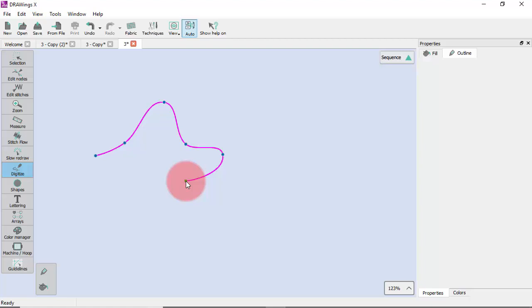While creating outline shapes, you may want some shapes to be embroidered together and others to be separate. For example, if you want this part to be embroidered together with the next one, they should be sections of the same object. To finalize this section, right-click to access the Action menu. The available options are Finish Section, Close Section, and End Shape.